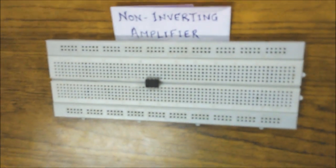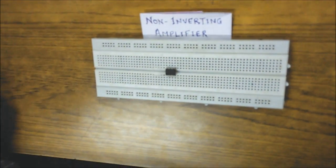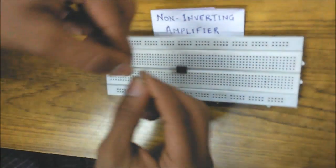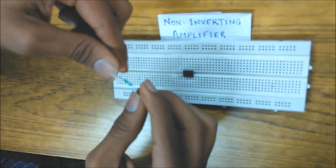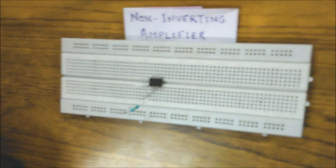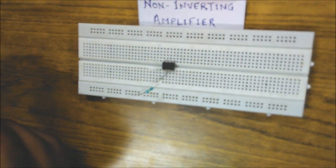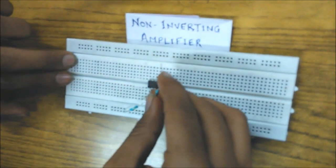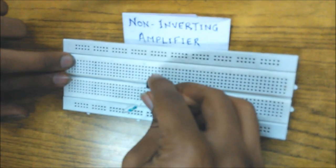Now there are two resistors which have to be connected on the breadboard. As you see, each resistor has two legs. We will connect the end of the first leg of the first resistor to pin number 2 and the other leg to ground. Similarly, the first leg of the second resistor goes to pin number 2 and the other leg to pin number 6, which happens to be the output of the op-amp.